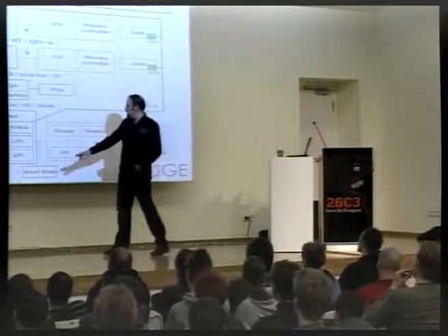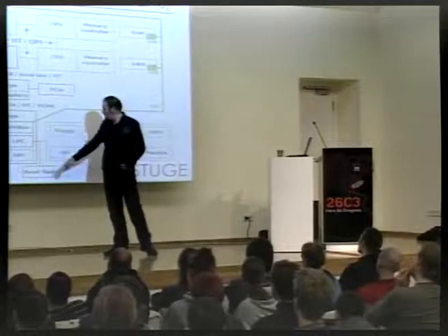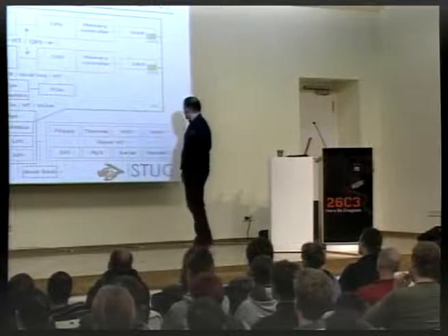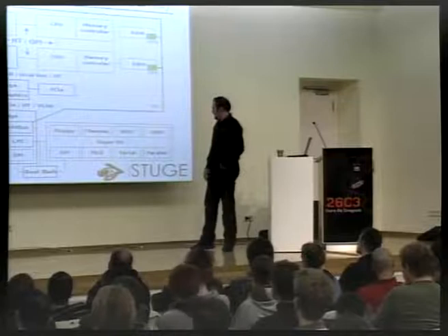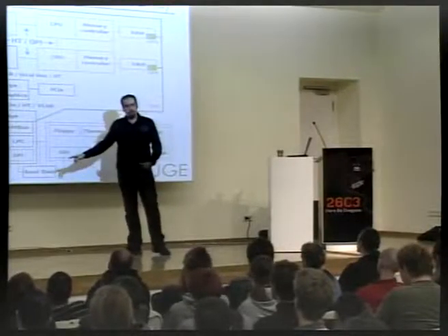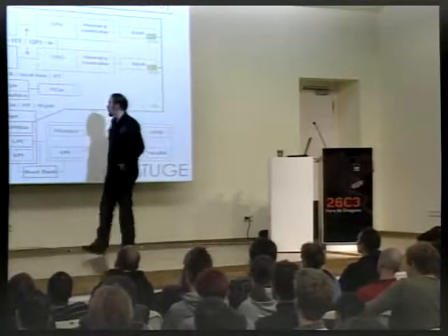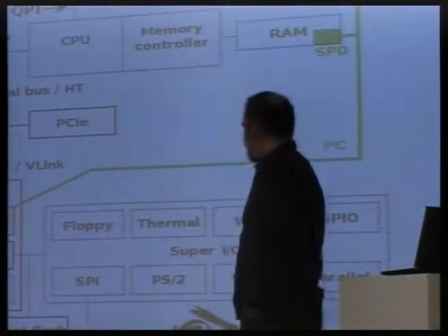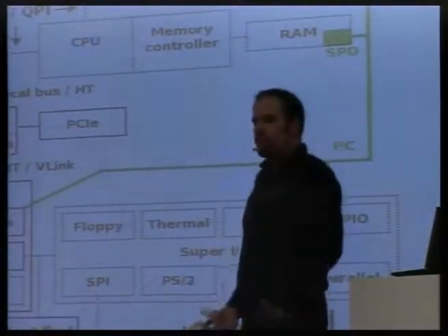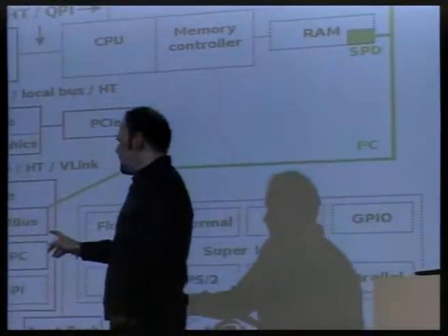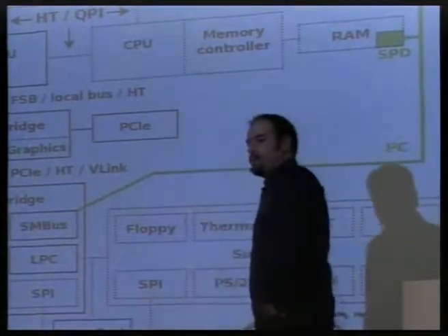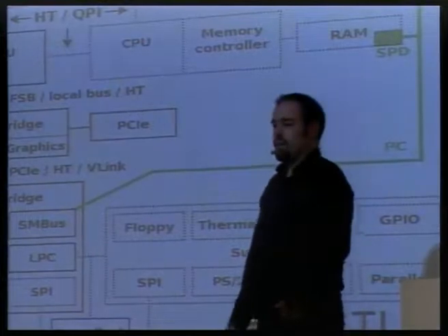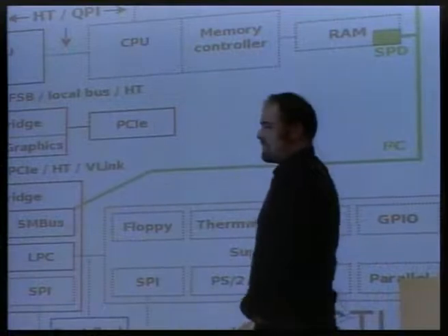So this is connected to multiple places because sometimes the flash chip is connected to LPC directly. Sometimes there's this SPI busmaster inside the South Bridge, but sometimes there's also this Super I/O chip, which does a lot of other stuff. And it can have an SPI master over here, and then the boot flash can be connected through there instead, and over LPC, and all the way up. And this can be a lot of fun. During my time hacking on Flash ROM, I discovered that decoding works by default. That's fine. It comes up the right way. But this SPI master, it's kind of limited. SPI supports 16 megabytes of address space, but one Super I/O vendor decided to save on 4 of those bits in their register space, so you can really only access half a megabyte of flash chips instead of 16. So that's too bad if you wanted to upgrade your flash chip.